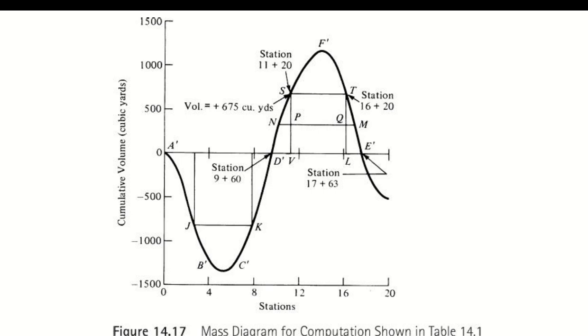Yes, good. We connected the points by hand, or we let the software do it, whatever the reason is. Between the two points, the software is working by itself, freehand; it's not following any curve. If you calculated a point after every 1 foot and then plotted it, that would be more accurate. But we didn't do it. Between each two points we have a gap of 100 feet, and 100 feet is a lot.